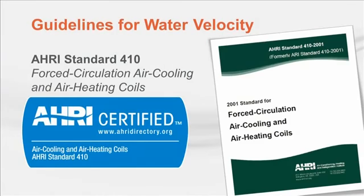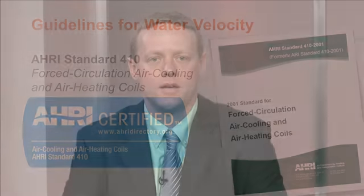Most coil manufacturers rate and certify their performance selection programs using AHRI standard 410. This standard establishes a single set of testing and rating requirements for determining capacity, as well as air and water pressure drops for cooling and heating coils. This provides design engineers with an apples-to-apples comparison of coil performance from manufacturer to manufacturer.